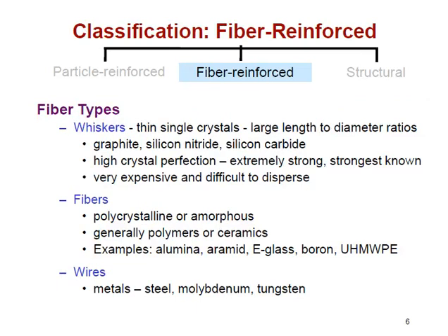Okay, reinforcement types. Basically got 3 different types, of which fibers, again, are the most commonly used. We'd mentioned silicon carbide whiskers in the 6061 aluminum example earlier as being an example of a ceramic reinforcement in a metal matrix composite. Whiskers are fairly expensive. They're high aspect ratio, thin single crystals, rather expensive to grow. They tend to be, again, ceramic in nature or graphite, very brittle. Very limited number of defects, dislocations, so they're very, very strong.